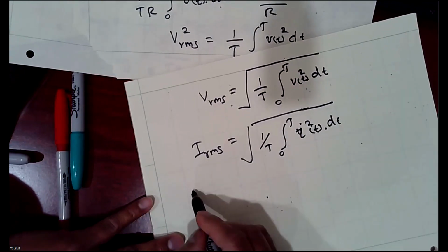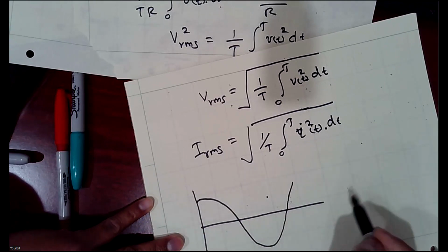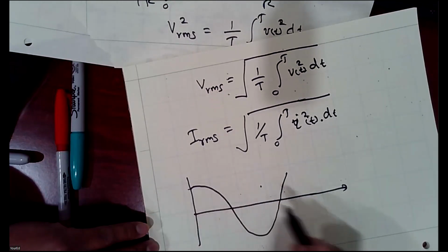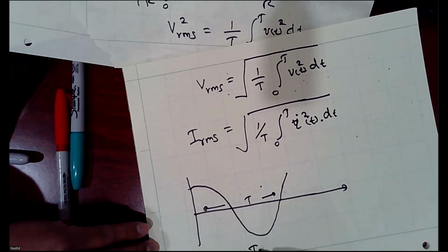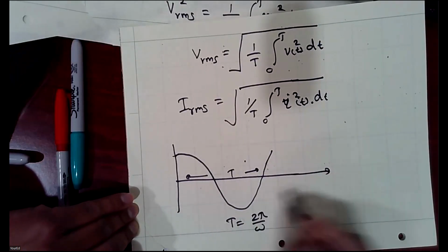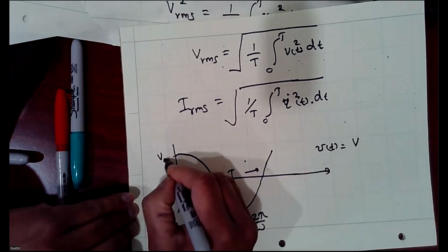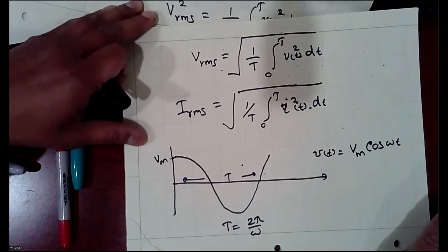Now, as we discussed before, our voltages are sinusoidal or cosine in nature for many electrical circuits. So if it is cosine in nature, if this time period is T and T is 2 pi over omega, therefore you can write this waveform in an equation like Vt is equal to, if this peak value is Vm, Vm cosine omega t form.